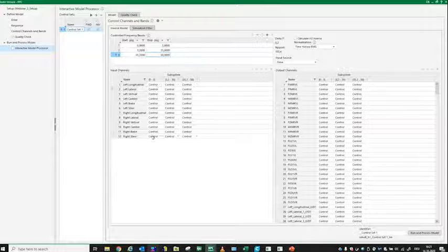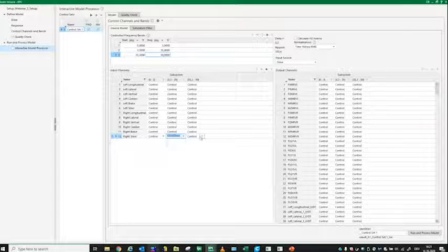And then what we are doing is we're just setting, let's say, the steer on control for 0 to 3 hertz. And then we go up and say here, no control for the further parts. And this steer on the other side as well, just an example here. And for the brakes, we do the same, except we just want to have it controlled to 35. So we say the left brake and the right brake will be just controlled up to a frequency of 35. So these are the settings I made, and now I can go to the right side and do my settings as well and have some examples here.